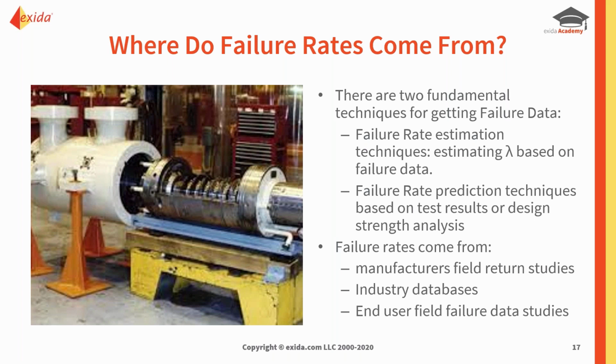And one of the problems with manufacturer field return studies is some agencies are not taking a view. They're simply taking the data that the manufacturer has given based upon, we've been manufacturing these devices from this date, we've supplied this many, we've had this many come back, and they base it on that time frame as being the operational hours, and then they come up with very, very optimistic failure rate data.